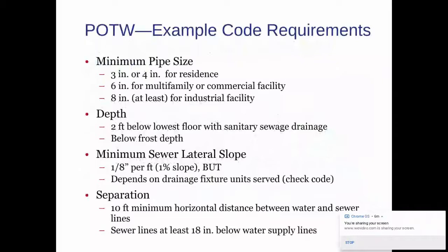There are places, a lot of basements. If you have a basement with a toilet, you might have a pump that pumps it up to maybe 3 or 4 feet, 5 feet above that. Just because here in the Chicago area, everything's so flat, we don't always have the ability to have it below the basement, but it might be 2 or 3 feet below the first floor. But it definitely also needs to be below frost depth, right? You don't want these pipes freezing and having issues during the winter.